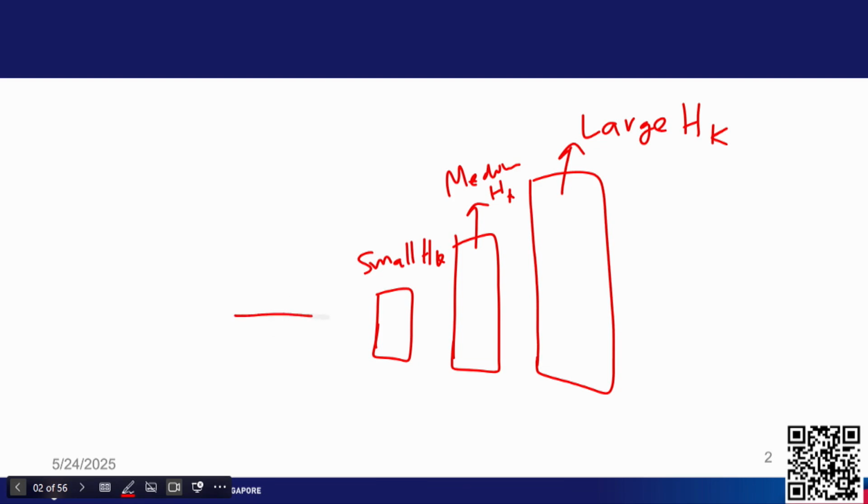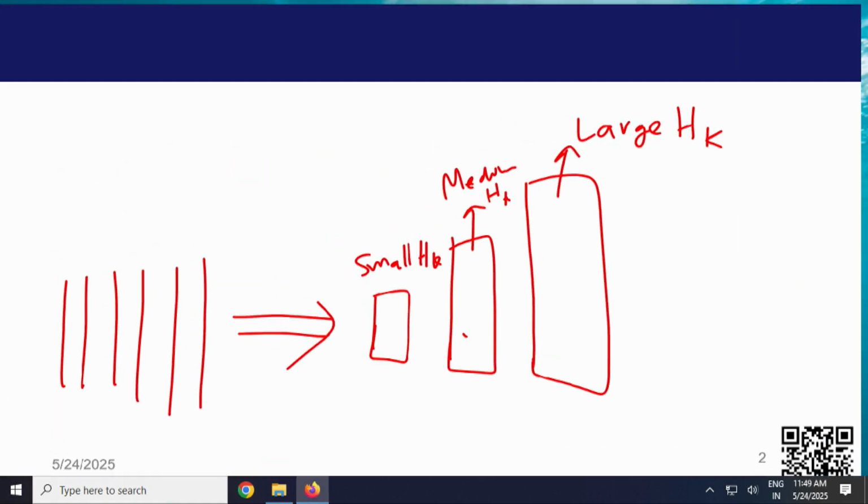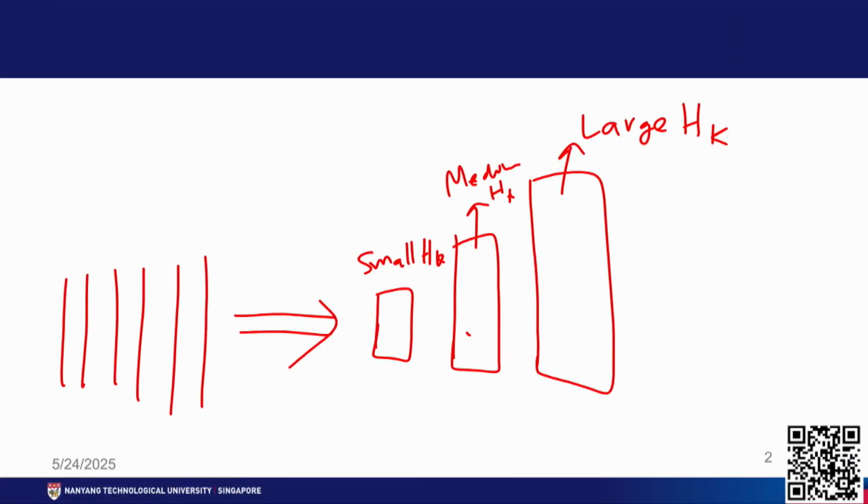So, when you apply a magnetic field, you are reversing the magnetization of this layer and that cascades to the next layer and so on. Okay. So, by having many layers with a different anisotropy field, and if a magnetic field is coming from this side, the magnetization reversal will cascade to the larger anisotropy layer.